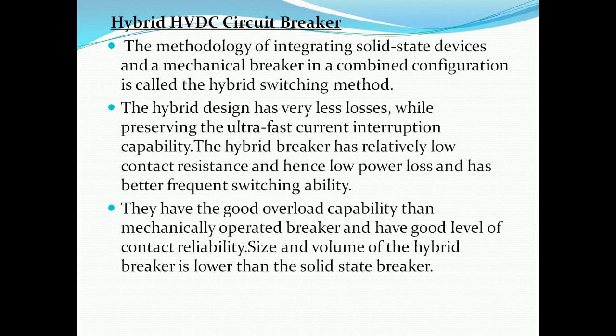They also have a good overload capability compared to a mechanically operated circuit breaker, and a good level of contact reliability. And the size and volume of a hybrid breaker is lower than that of a solid state breaker.